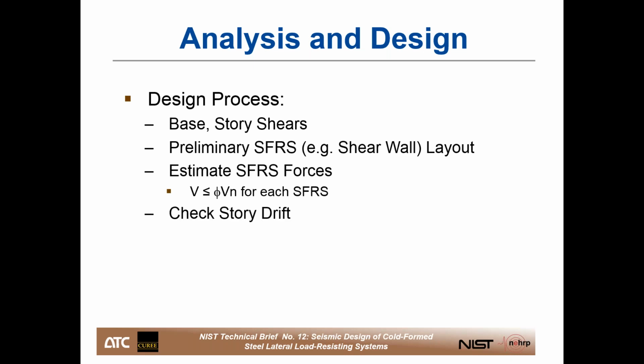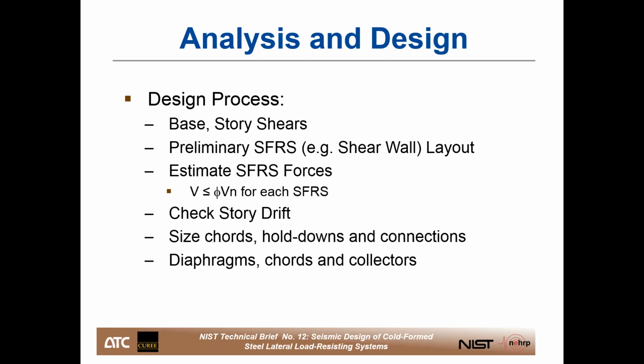Then we would check for story drift, compare that to the code limitations. And with the configuration finalized, the specific parts of each seismic force resisting system would be designed, including the capacity protected components like chord studs, hold downs, and connections, and then the system can be detailed. We'll talk a lot about what I mean by capacity protected components as we go through the webinar. And then diaphragms could be designed. And if necessary, based on the diaphragm rigidity, the seismic force resisting system forces could be reanalyzed in what could be an iterative process.